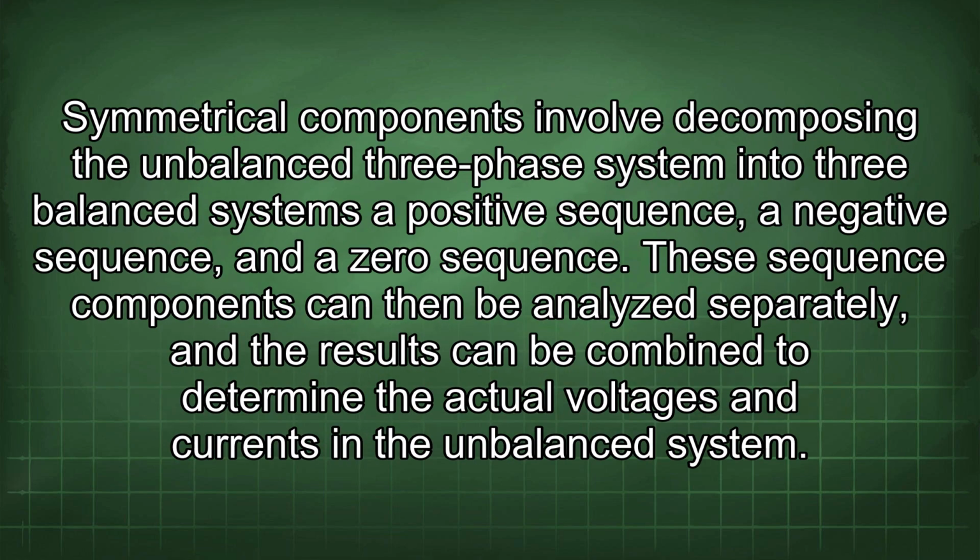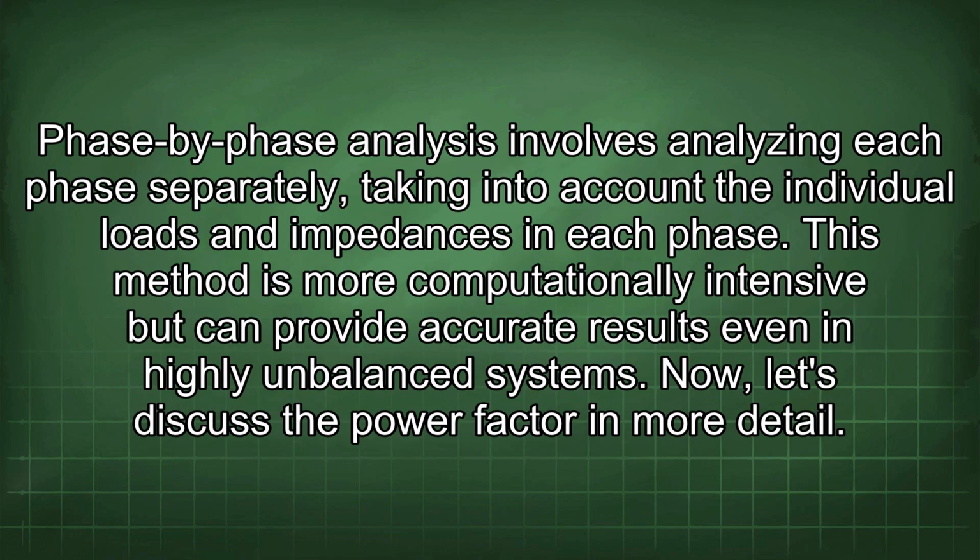Symmetrical components involve decomposing the unbalanced three-phase system into three balanced systems: a positive sequence, a negative sequence, and a zero sequence. These sequence components can then be analyzed separately, and the results can be combined to determine the actual voltages and currents in the unbalanced system. Phase-by-phase analysis involves analyzing each phase separately, taking into account the individual loads and impedances in each phase. This method is more computationally intensive but can provide accurate results even in highly unbalanced systems.